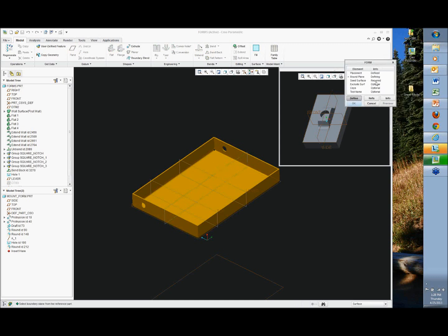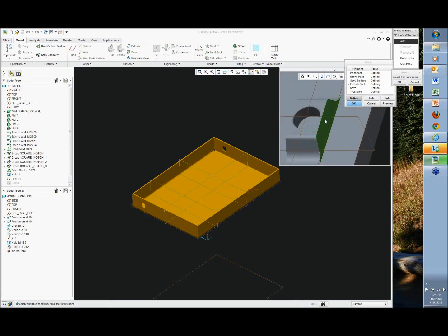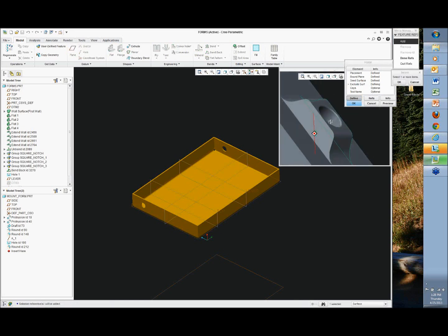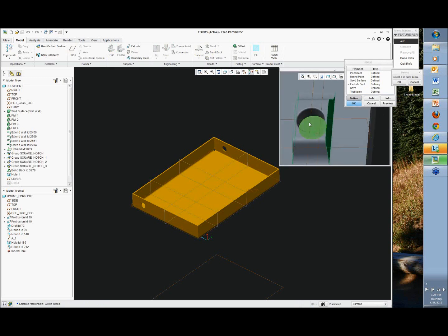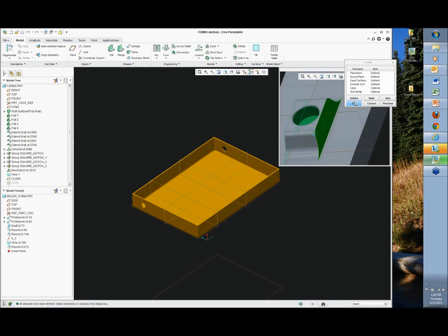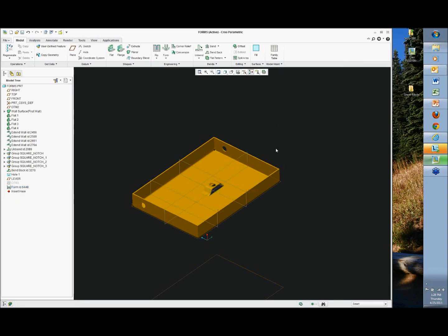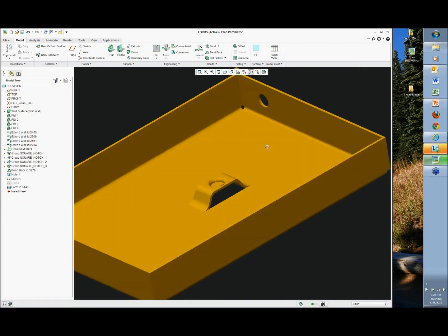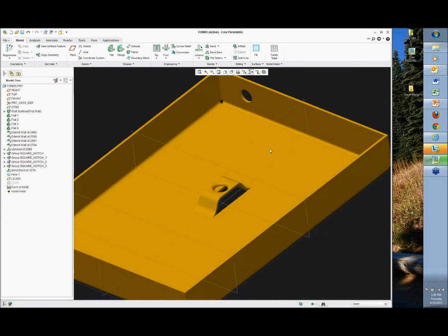It still has some of the old dialog box type stuff where I have a seed surface and bounding surface. Seed is the top, so bottom up. And then exclude surface. So what this does is I can remove things like that side surface, which makes sense, the bottom of the hole, maybe even the sides of the holes. Right? Done references, say OK. And there's my form.